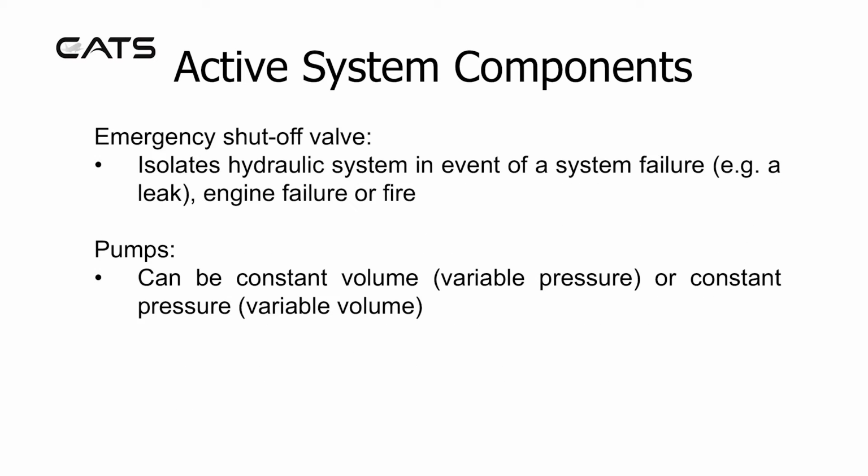The emergency shut-off valve. This isolates the hydraulic system in the event of a system failure, for example a leak, an engine failure or a fire. Pumps can be constant volume, variable pressure, or constant pressure, variable volume.